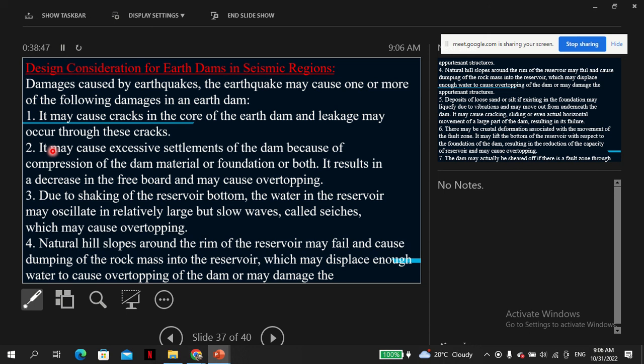If you design against 7, that means if an earthquake occurs, the building is safe. It might incur some little damage which can be rectified, but the building can still be in service. Now, if anything above that occurs, the building can fail, but it cannot catastrophically collapse to kill people. People can be saved. Of course, the building can no longer be serviceable, but at least the objective is you save people. So this is the idea here.